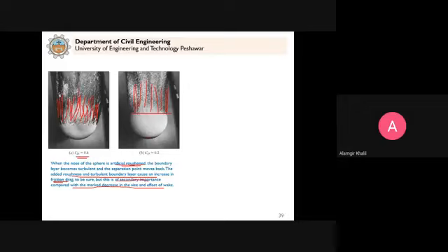You can see here the effect and size of the wake, so it has shifted from here to here. So of course this will increase the friction, but this is the most important thing that has occurred. As a result, the drag coefficient is reduced to 0.2 as compared to 0.4. So you can see that compared to smooth, with roughening the surface this body will move faster through the water. Clear?